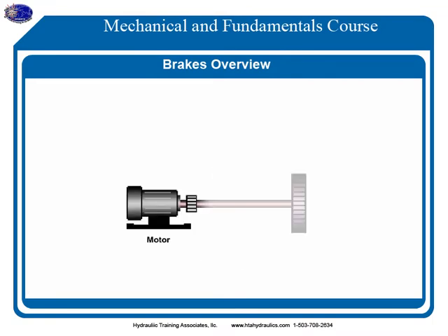To see how a brake operates, we will construct a simple machine system without a brake. The flywheel, connected to the motor shaft, acts as the load to be stopped. Since motors cannot stop the load when turned off, the load of the flywheel will coast to 0 RPM. If rapid or precise stopping of a load is required, the motor cannot control either of these functions. This is an immediate indicator that a brake is needed to stop the load at a rated speed.